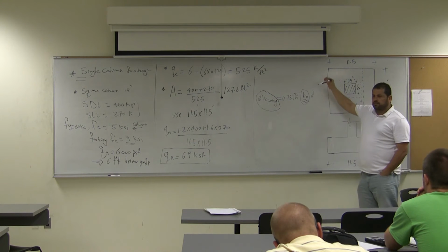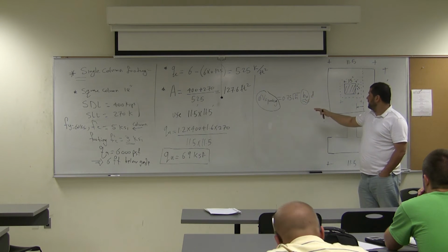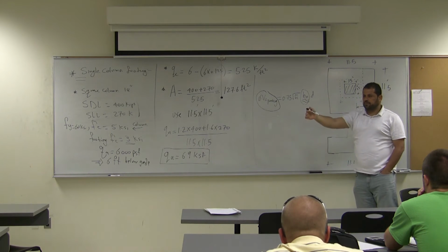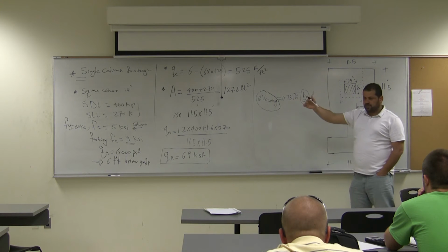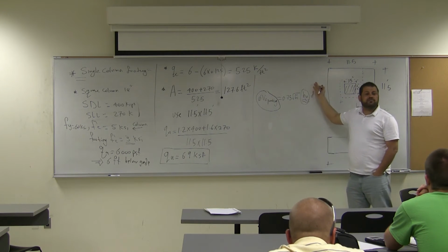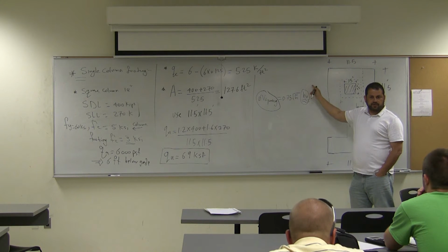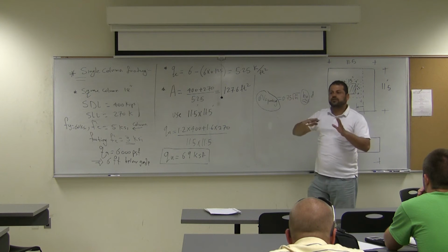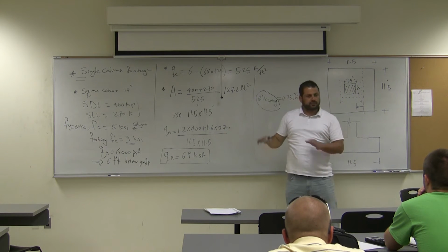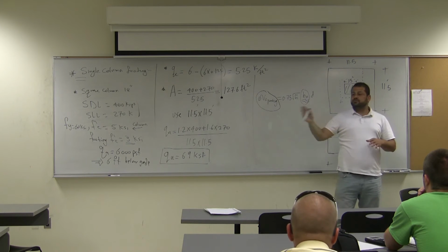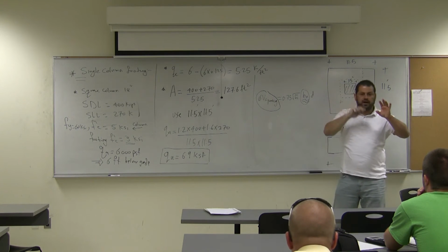By the way, if you want, you can calculate Vu2, Vu punching, in terms of d, and you can calculate this one also in terms of d. It will be a square equation. Then you make them equal. That's not practical, but you can do it if you have a fast calculator, then calculate the required width. Or just assume d. Your first assumption will tell you where you are.